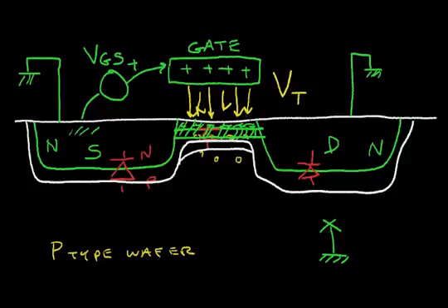It becomes lower resistance because we have a greater path for current to flow laterally in this region. Now, as we apply a very strong gate voltage, we drive this channel region down even further, and the resistance of this channel region becomes less, and this depletion region will be driven down further.